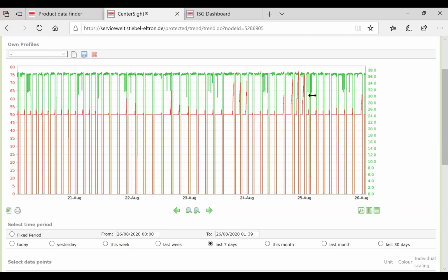It is jumping around a bit, but not a lot, between 32 and 37 liters per minute. The nominal flow rate on a WPL 25 is in fact about 24 liters per minute, so we are well exceeding the nominal flow rate. The minimum flow rate is 15.